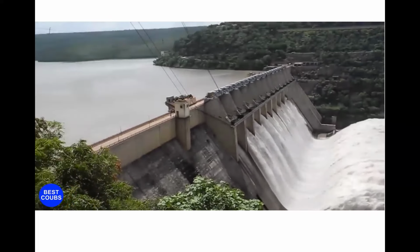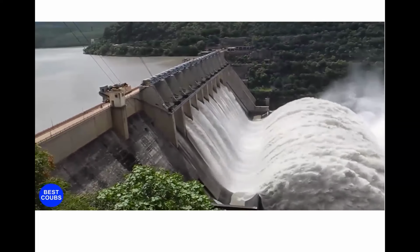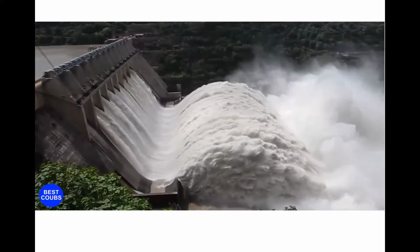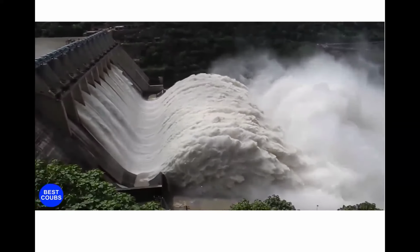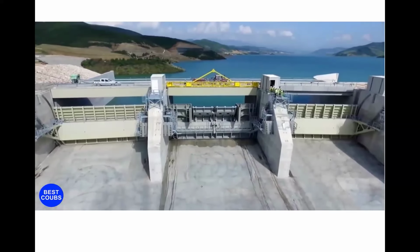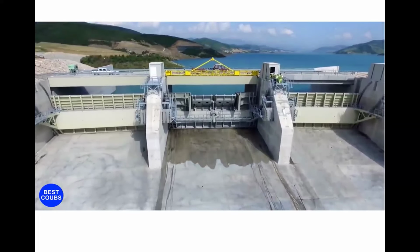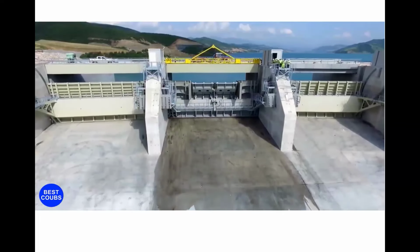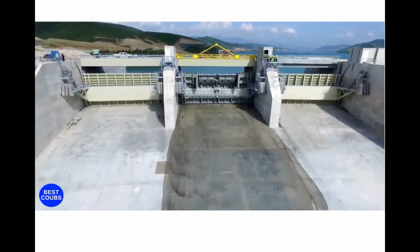Yeah, OG spillway, very, very familiar shape now, right? Flow coming down, and then sometimes you see that this actually doesn't have a typical supercritical flow with a jump that we have been talking about. This is common. It happens very commonly in hydraulic structures. Sometimes they have these and they just discharge flow and let the jet interact with the air and dissipate, and then come back down, not like a splash, but a very much diffused and dissipated jet comes down.